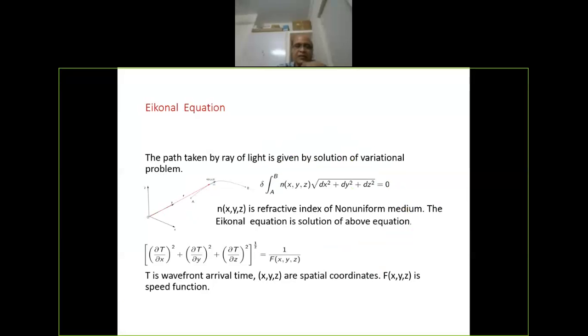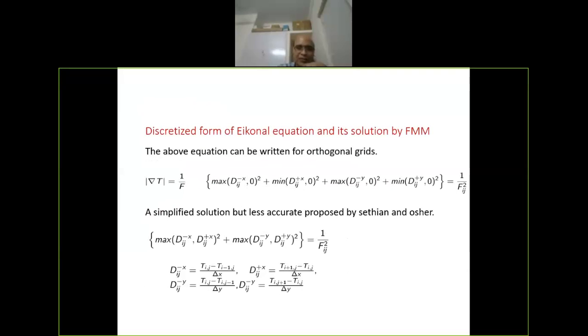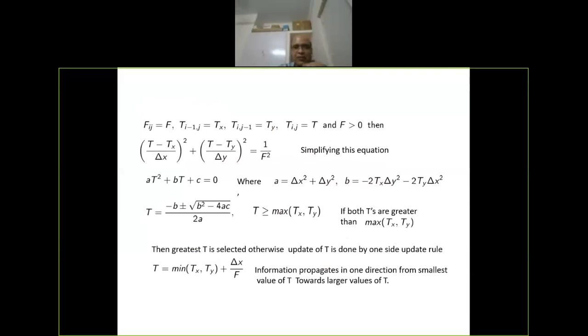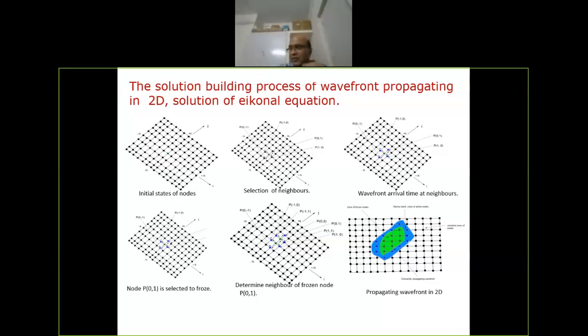Now, so how do we do the path planning for this kind of a robot which can go on three-dimensional terrain? There are many algorithms. Maybe when I talk tomorrow, I will talk about some algorithms of path planning and motion planning. So one algorithm which we use here is what we call the wavefront propagation using the eikonal function. The wavefront propagation is like the way the waves move, okay, on the surface of a lake or a pond. If you drop a stone, then the wave will be generated and the wave is going to move.